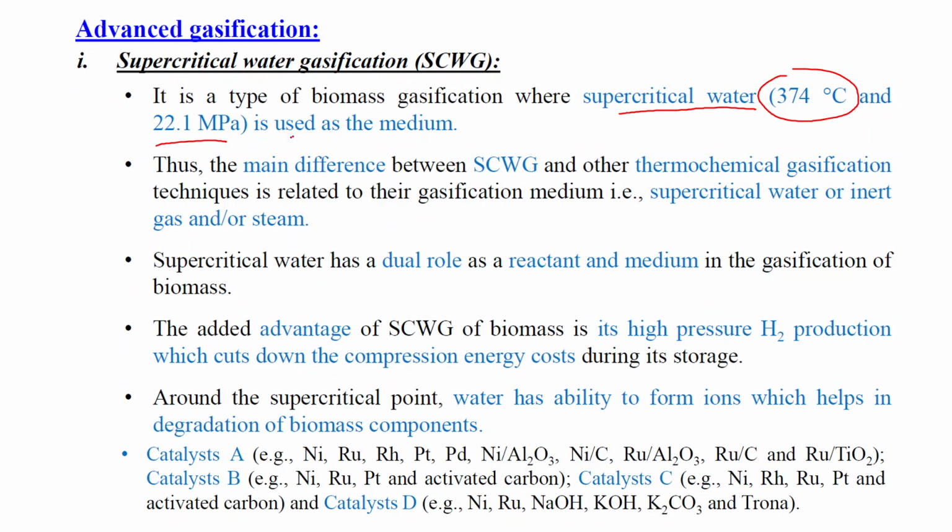It is a medium basically for heating, as well as a raw material. The main difference between supercritical water gasification and other thermochemical gasification techniques is the gasification medium. There we are using simple steam or water, but here we are using supercritical water in an inert atmosphere. We are not using air or steam. That is the main difference.